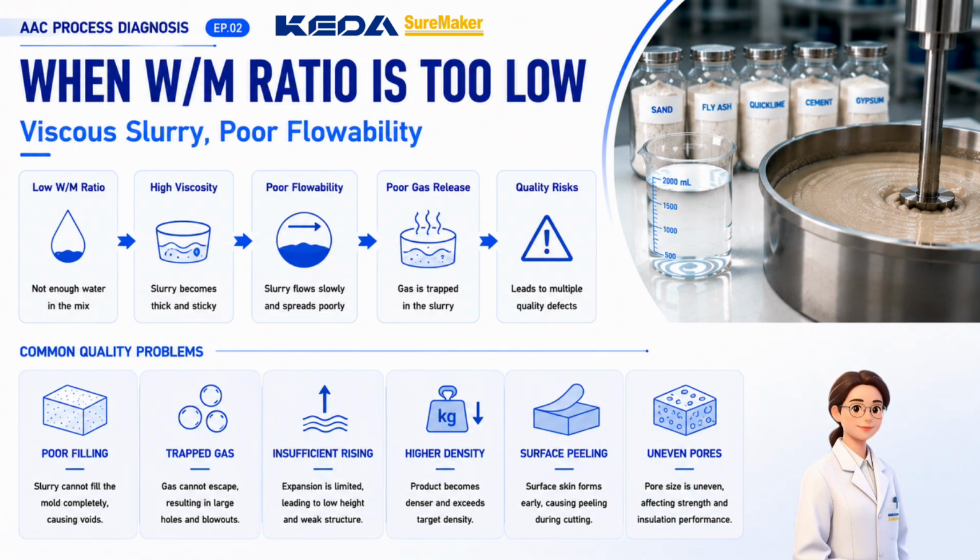But we should also note that these problems are not caused only by the water-to-material ratio. For example, gas generation quality is related to aluminum paste. The length of pre-curing time is related to quicklime dosage and available calcium oxide content. Slurry viscosity is related to sand slurry fineness and the properties of the sand itself.